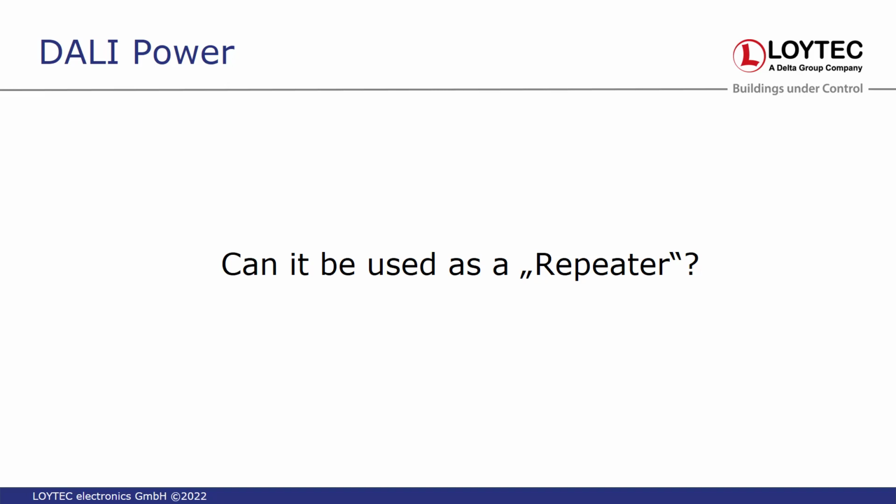When you have a longer channel, actually there are DALI repeaters out there, so they would be on the channel and they would really refresh the signal, and you would have a galvanically separate channel. So yeah. Then you would really need a DALI repeater, but you cannot do this with a power supply.